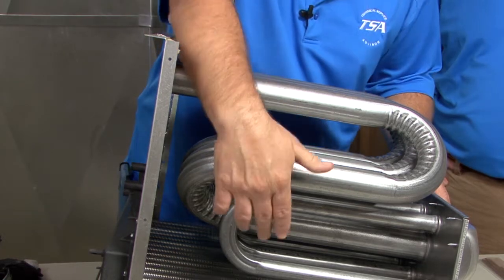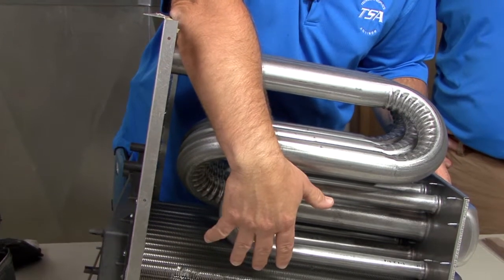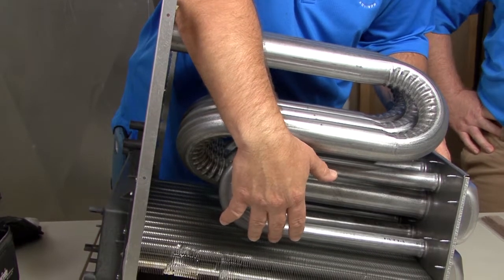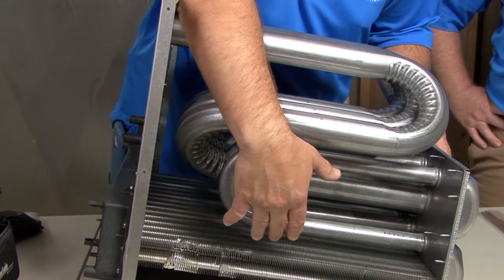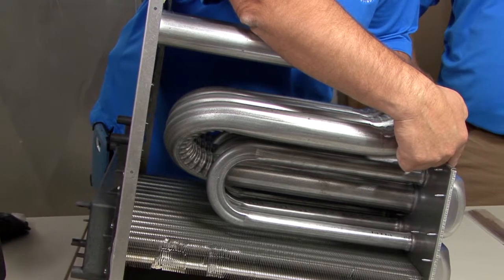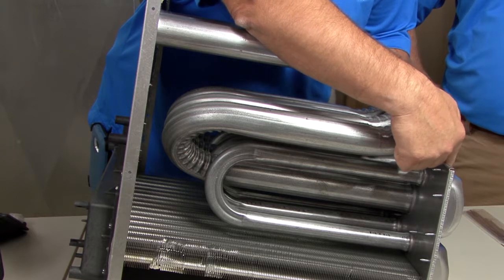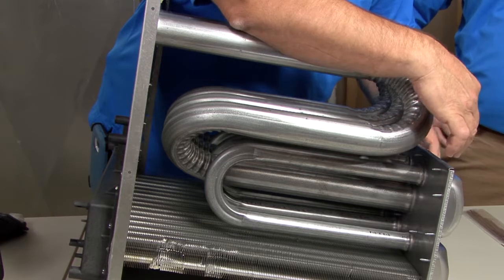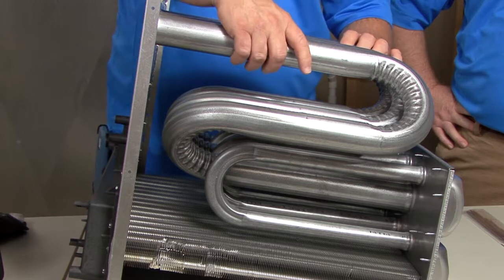Same as if you have a hole down here in the secondary. If you've got a hole in the secondary tube anywhere in there, you should be able to pick that up on the smoke test, and it'll actually affect the smoke in the primary cell, even though it's way down here, because this is all interconnected through the back collector on the back of the heat exchanger. So even if you've got a seal problem back here, you'll pick it up. It really doesn't matter where the problem is, whether it's in the tube, in where the header assembly is, where your primary and secondary come together, or in the primary tubes themselves.